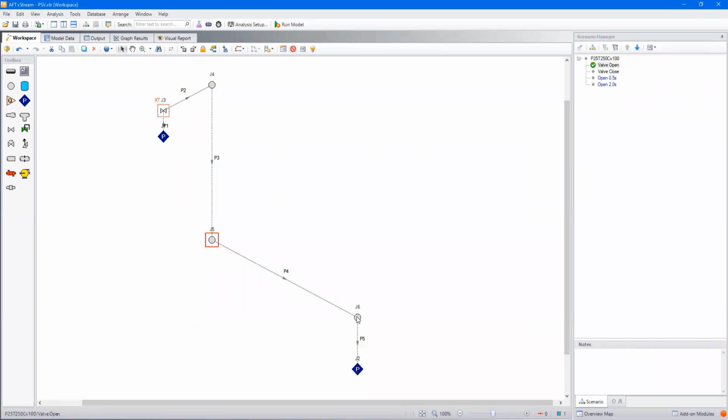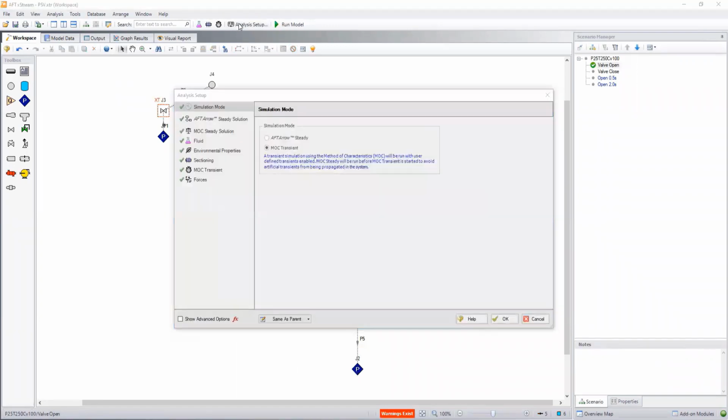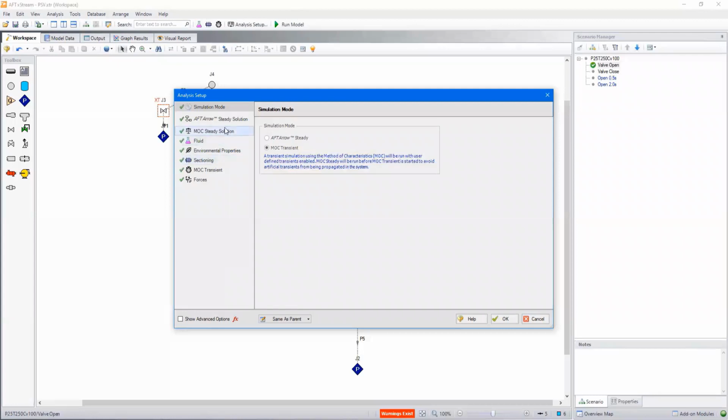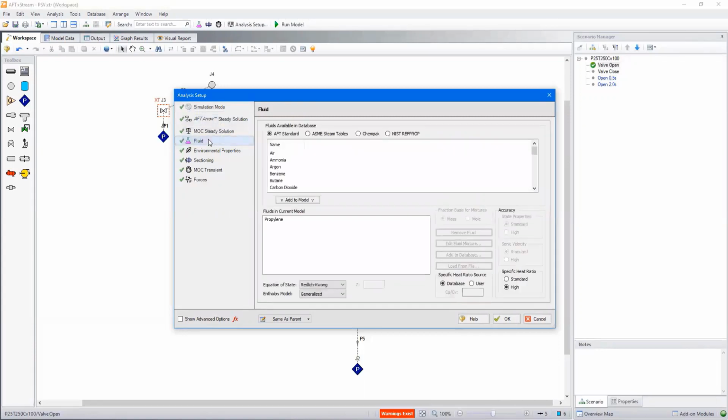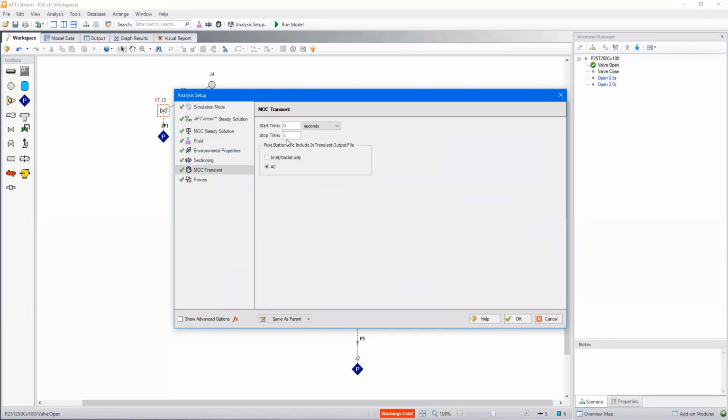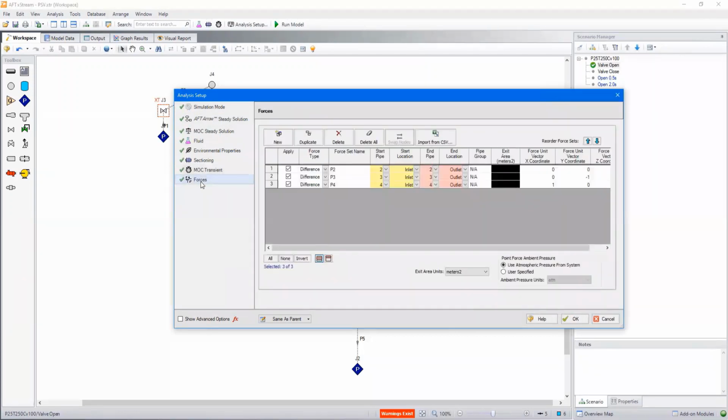I've also defined a couple of junctions here, which is what you need to do when you're defining piping forces in xStream. If I have a look at the general input parameters, you can see here that I've inserted propylene. There's a huge variety of fluids that we can use from all sorts of Chempacks and other databases. We've got a start time of 1 second, a stop time of 1, and I will now have defined a number of locations where we want to get our forces out.